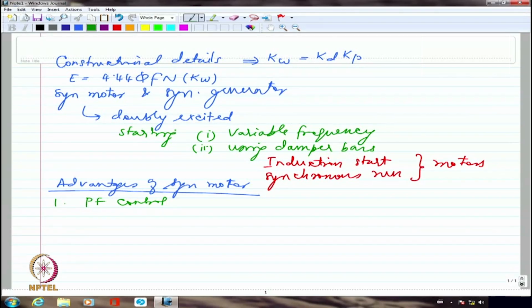So, I may be drawing a magnetizing current from the armature side. If I am having a shortfall in flux, I may draw no magnetizing current at all. If the flux is just sufficient, I might return some amount of reactive power to the three-phase mains if I am having excessive amount of reactive power fed from the rotor side.